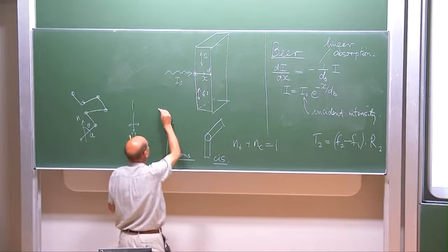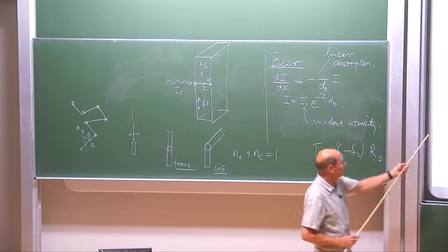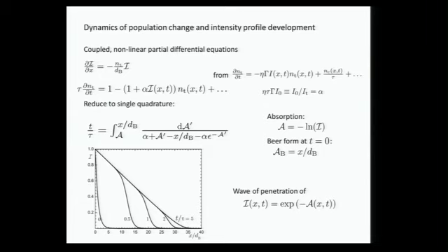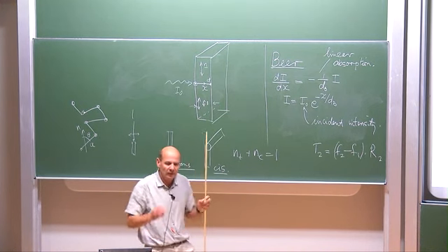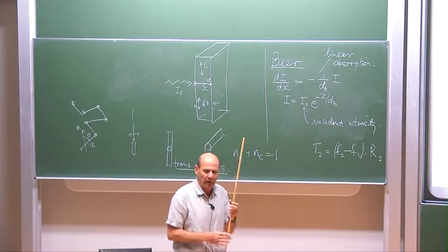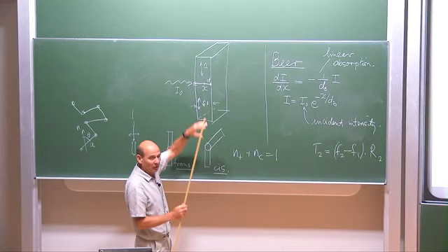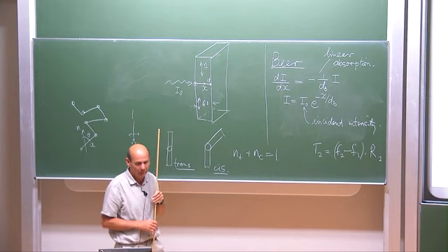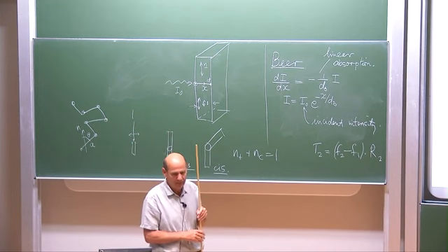Yes. The light intensity gradient is exactly this. So at a given time, as I go in, depending on where the thickness of the sample is, I will have this variation of the intensity of light. And then the stress this way, well, the sample is thin, and the surface tractions are 0, and so within the normal approximations, for instance, of beam bending theory, you say that the stresses this way are 0. From an elasticity theory point of view, plane stress. Yeah, plane stress, exactly.